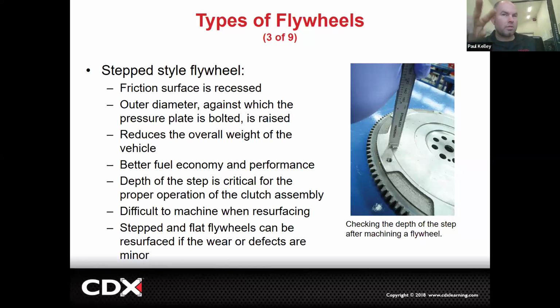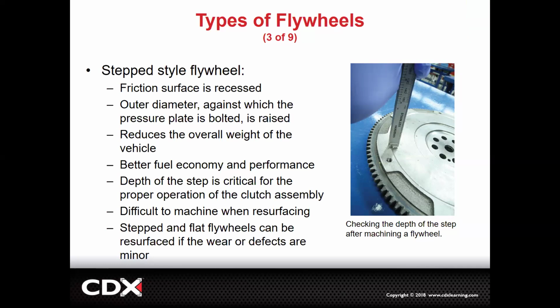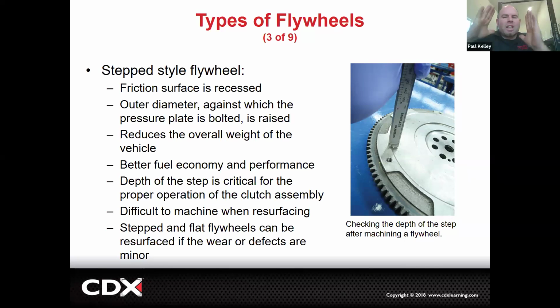I'll give you 2 options. Slipping and dragging is mostly what we talk about. So it had 30 thousandths clearance, now it has 40. It's going to slip or drag. Slip. Exactly. It's going to slip because it's not being squeezed as much. You're exactly right.